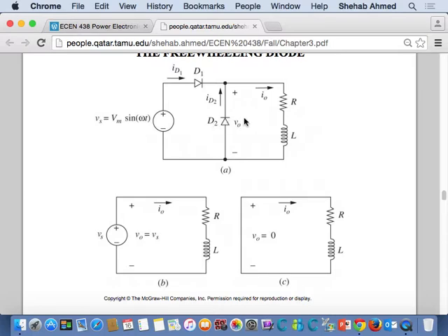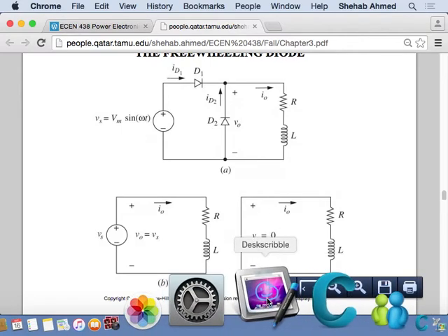Okay. So now we have reviewed this circuit, and then we will do the same thing. We want to find the equation for the current, because the voltage looks like a half-wave rectified sine wave, right? Because as soon as we put the freewheeling diode, it's very simple. The half-wave rectified sine wave, we know the equation for voltage, right? How about the equation for current? The equation for current in the load is exactly as before, right? Did the current change shape? The load current.